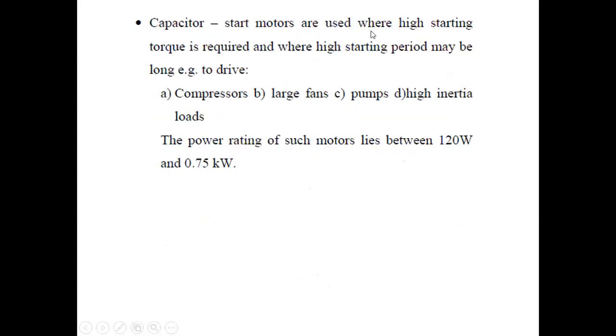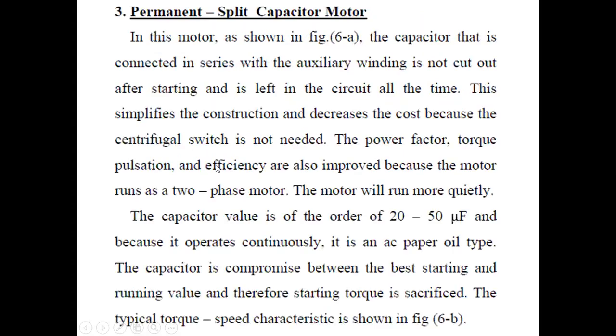Capacitor start motors are used where high starting torque is required and where the starting period may be long to drive. For example, compressors, large fans, pumps, and high inertia loads. And then we can see there's an improvement. So such motors range between 120 watts to 750 watts.